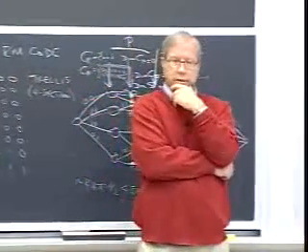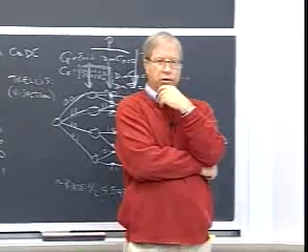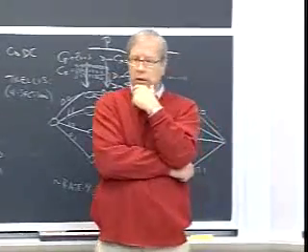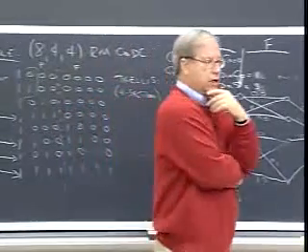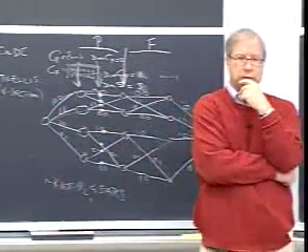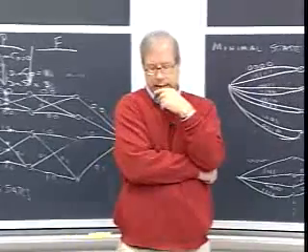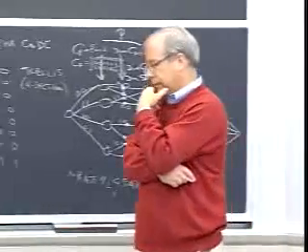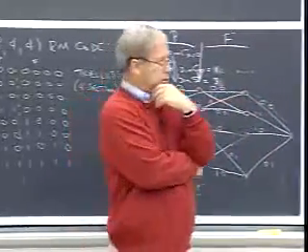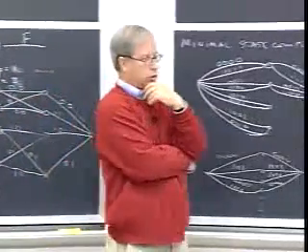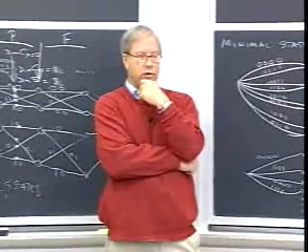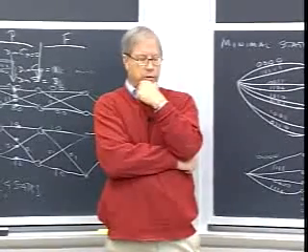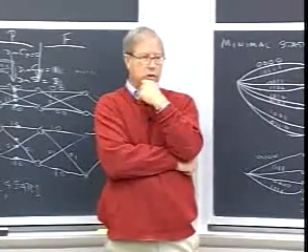Just by inspection of the trellis-oriented generator matrix, we can determine what the state space dimensions are at each instant of time, at each possible state cut, and we can then draw a trellis which achieves that minimal state space dimension, or minimal state space size, for every moment of time simultaneously.